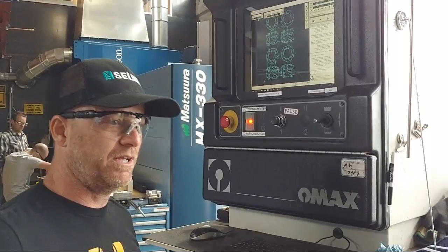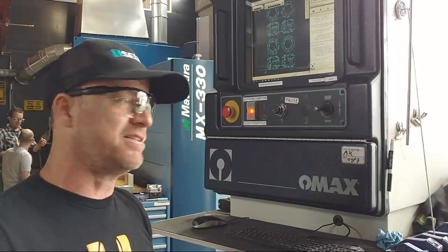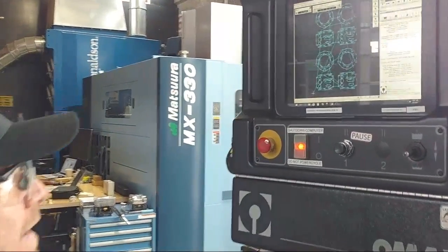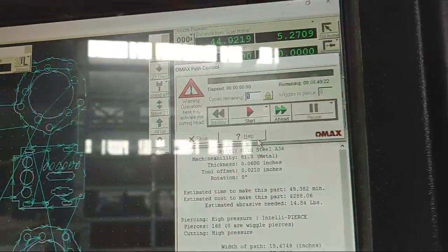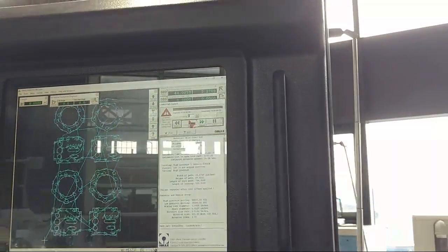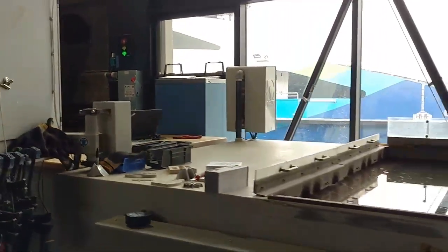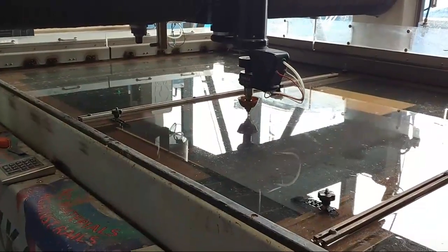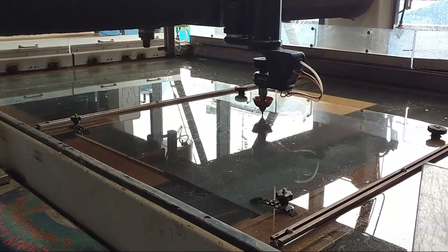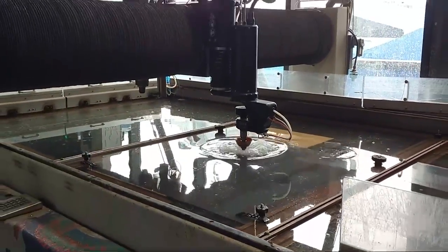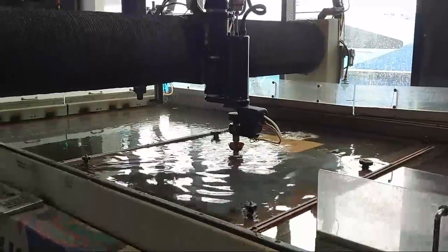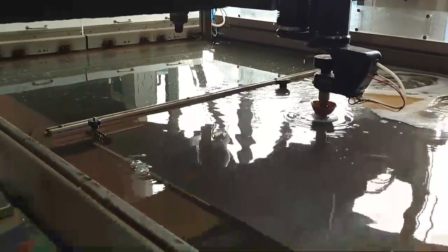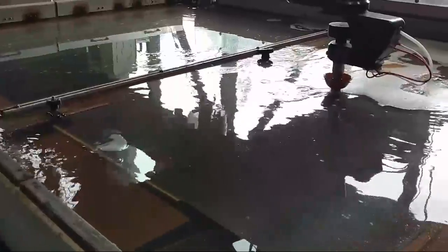So we've posted the code, we've set our X and Y, and we've set our Z. So what we need to do here is just begin machining. Just click on that. You saw that a little initial pierce where it pierced through the material. Obviously, if we had the boot on, we wouldn't have seen that splash, but otherwise this is a fairly boring process.